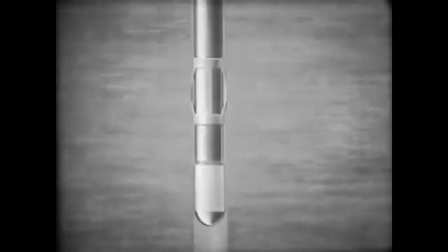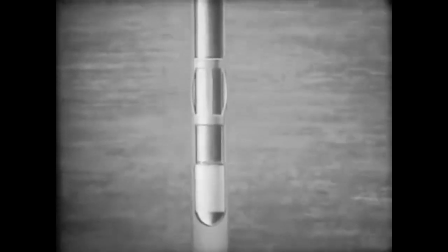The casing, like drill pipe, is assembled section by section, and each of them weighs a ton or so. These centralizers are fitted at regular intervals to keep the casing central in the hole as it goes down. The casing is lowered in until it reaches a point just above the bottom of the hole. The next job is to cement it home.